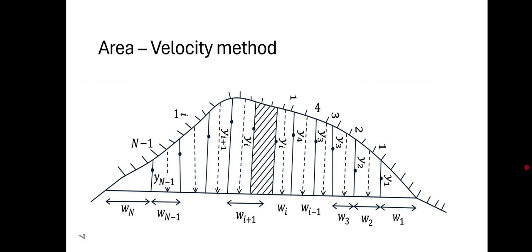This method of discharge measurement consists essentially of measuring the area of cross section of the river at a selected section called the gauging site, and measuring the velocity of the flow through the cross section area. The gauging site must be selected with care to ensure that the stage discharge curve is reasonably constant over a long period of a few years. The stream should have a well-defined cross section which does not change in various seasons. It should be easily accessible all through the year. The site should be in a straight, stable reach. The gauging site should be free from backwater effect in the channel.